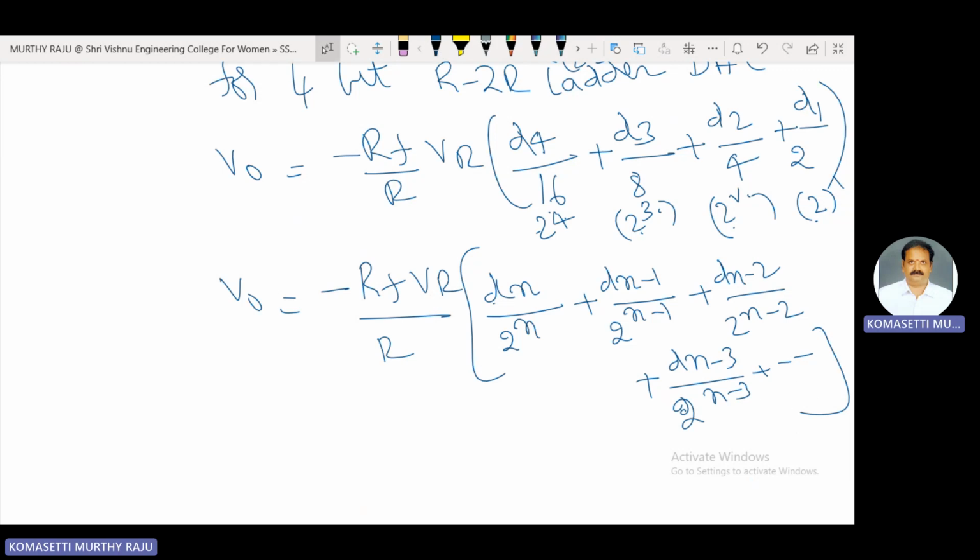This is the R-2R ladder. Here only two resistor values are used, R and 2R. In the weighted resistor type digital to analog converter and the R-2R ladder type digital to analog converter, the current flowing in the resistors changes as input data changes.